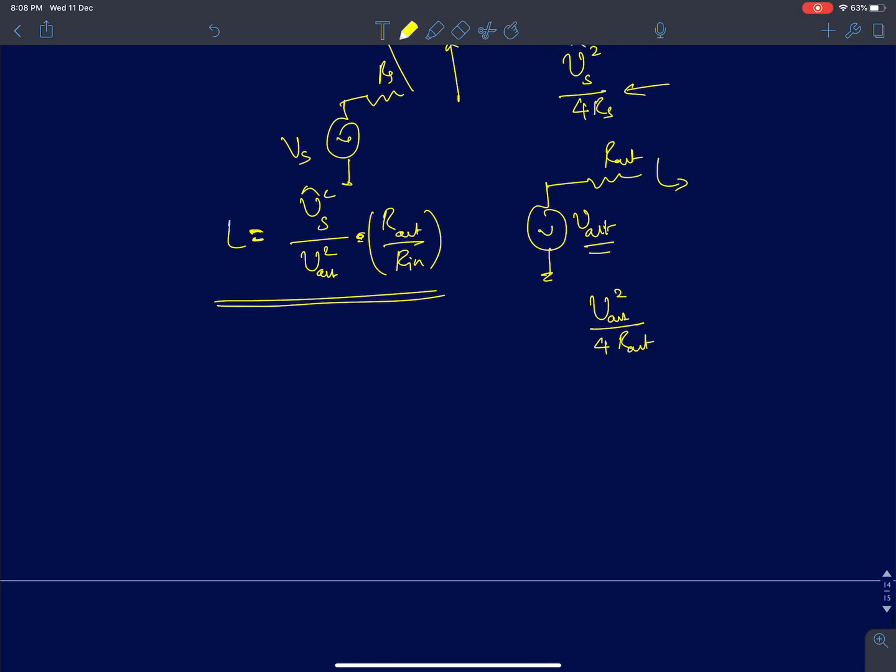Now there is one very important theorem for any circuit. Between the two terminals, when you look at the output of the bandpass filter, I can write it as a Thevenin equivalent. So there is a voltage source and an output resistance. There is also a theorem which says the Thevenin resistance here captures the loss in the circuit. So whenever you have a loss, that's going to create noise. The loss here is going to model the noise.